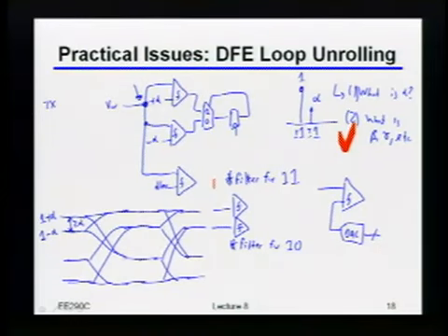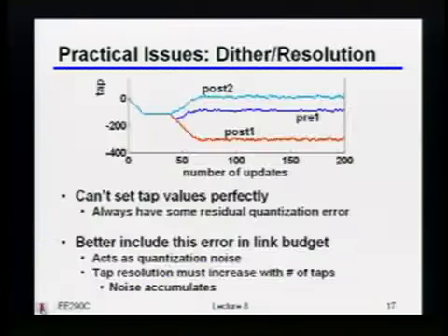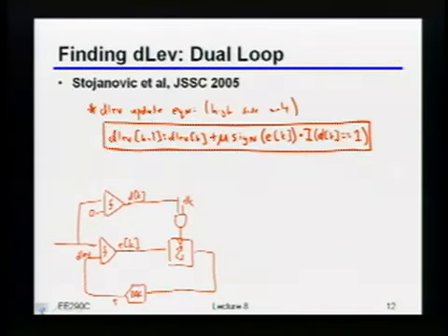What happens in the rest of the system? What do you do with those digital coefficients? What do they get fed to? A DAC. Yeah, they get fed to a DAC. Now, and this is maybe just a reminder, I'll go back to this hardware block diagram we drew over here. If I really had a loop like this, what's the only thing I care about from this DAC? What's the only design constraint on that DAC? Monotonicity. Okay, yeah, probably I want it to be monotonic, and maybe I want it to have a sufficiently small step size.